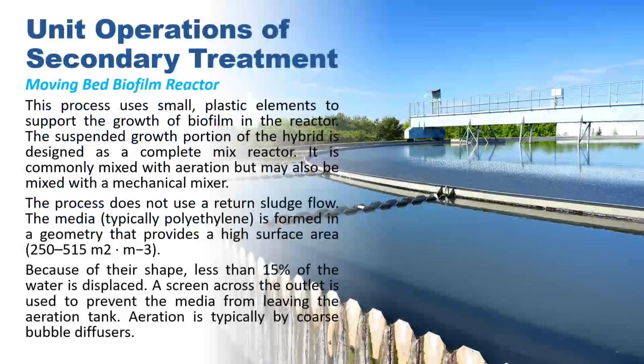Now let's move on to the moving bed biofilm reactor. This process uses small plastic elements to support the growth of biofilm in the reactor. The suspended growth portion of the hybrid is designed as a complete mix reactor. It is commonly mixed with aeration but may also be mixed with a mechanical mixer. The process does not use a return sludge flow.